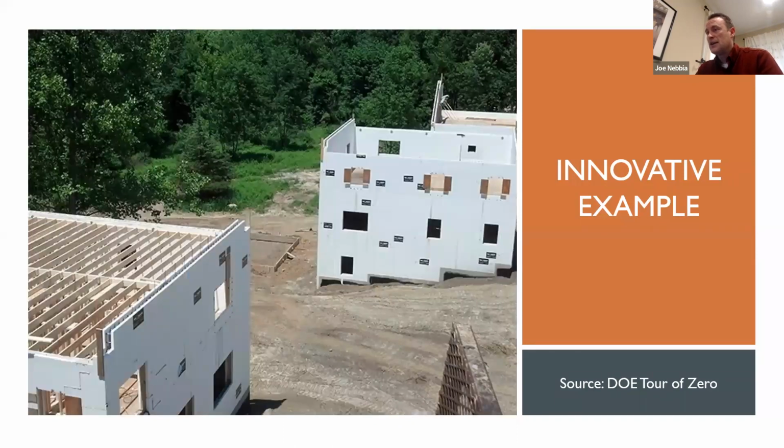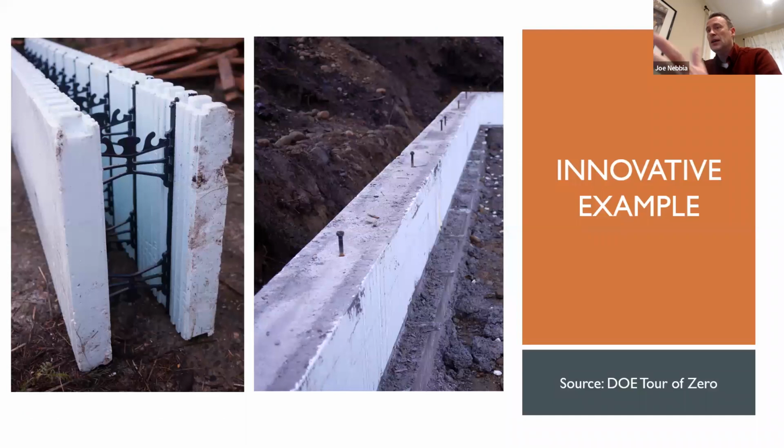This is an insulated concrete form. So it's two panels of rigid foam insulation, and concrete is poured into that as it's assembled in order to create a very strong and very airtight assembly. Here's a block of this, and it's usually built block by block on site and then poured, so that it doesn't come obviously filled with concrete, which is very heavy.